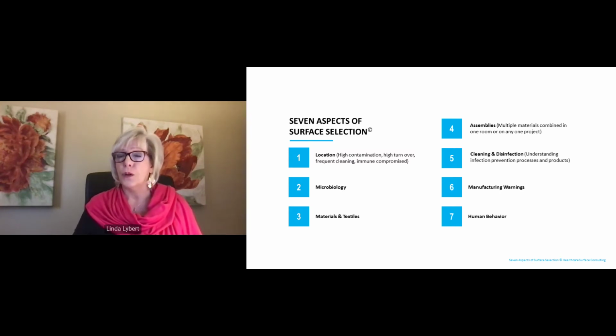It's not unusual for a given surface material to be cleaned 14, 15 times in a day. And you want to make sure that when you're selecting the materials, those materials can withstand that type of cleaning. Microbiology. When we talk about microbiology, again, emergency departments, a lot of different things are coming in and out. And depending upon the microbes, it requires different types of cleaning or disinfectants.